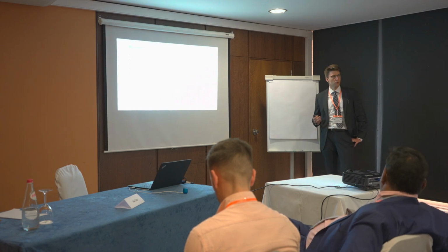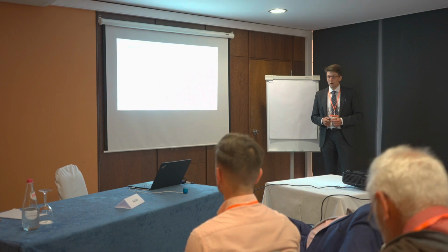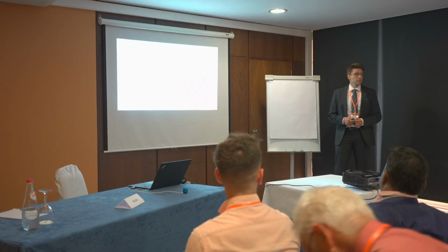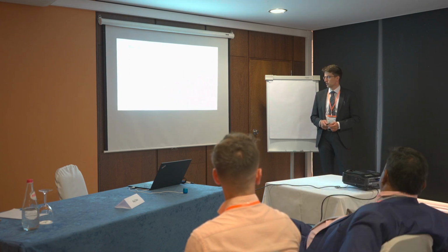We introduce a known pressure pulse, and then we assume a conservation of momentum, and then we can make the dynamic calibration. I will show you in the next slides how this works. But rearrangement of the bars is necessary to perform the dynamic calibration.